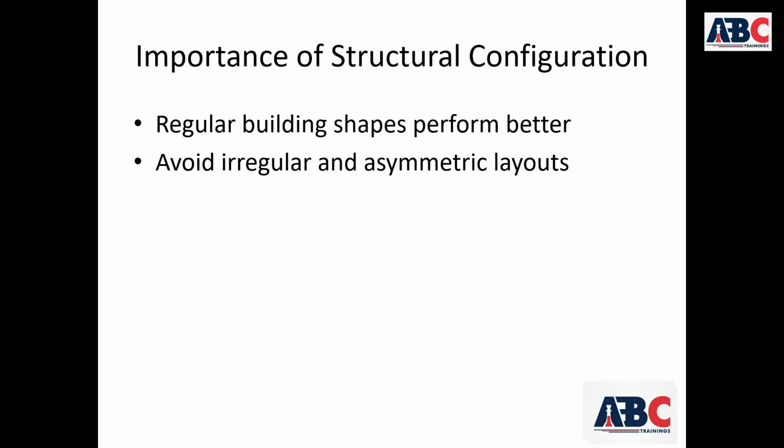Why configuration matters? When an earthquake occurs, forces act in vertical and horizontal directions. If the building's shape is simple and regular, forces are distributed evenly. Movement is uniform and stress concentration is minimized.